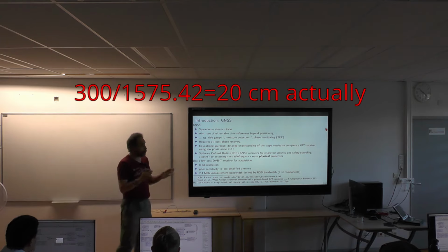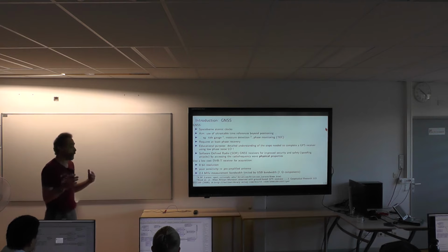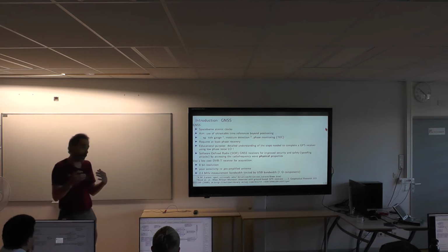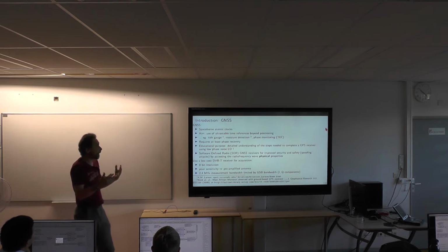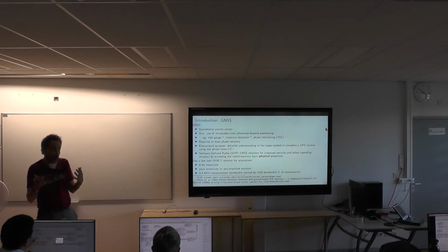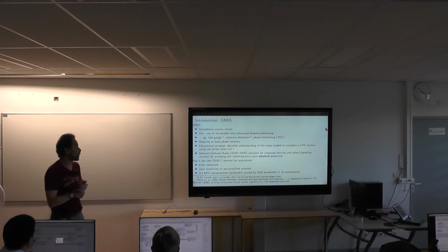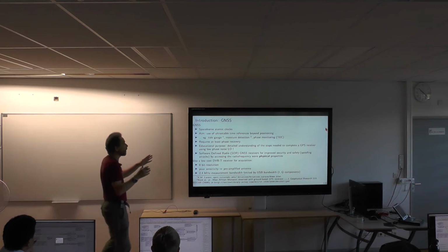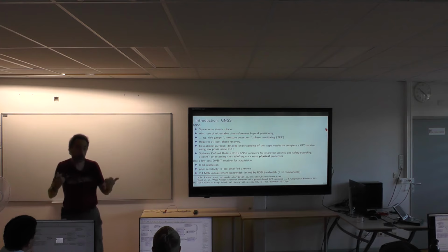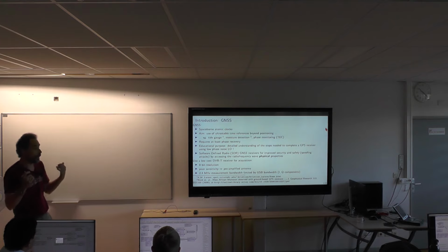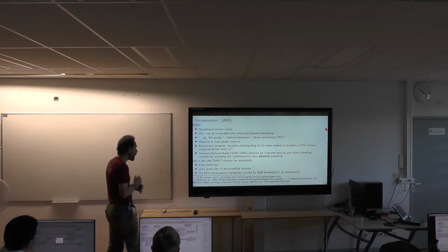And we're going to address all these challenges using records from software-defined radio, because using SDR, you can actually record the file once and replay or reanalyze the data as many times as you want, and you don't need to wait for the constellation to match again the same position that you had. Beyond the scientific purpose, the educational perspective is you have a full understanding of the signal processing, and you can really understand the details and the limitations of processing.